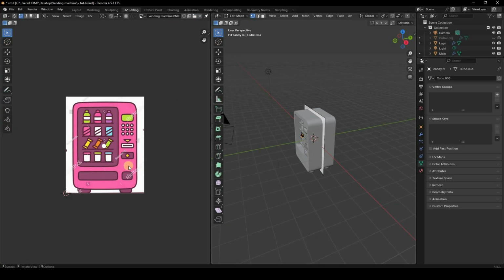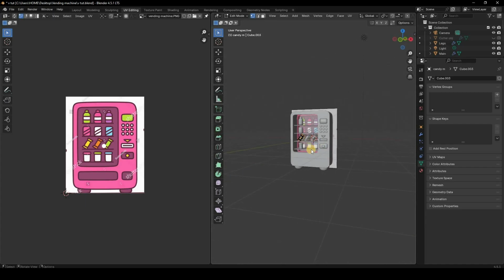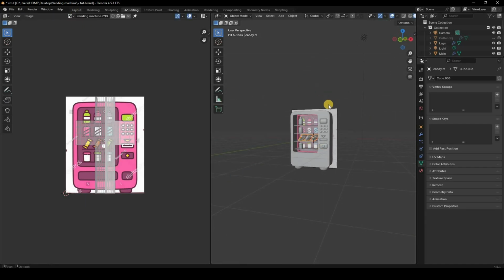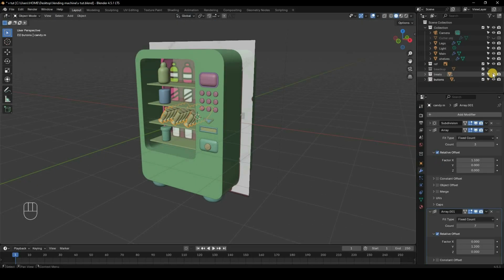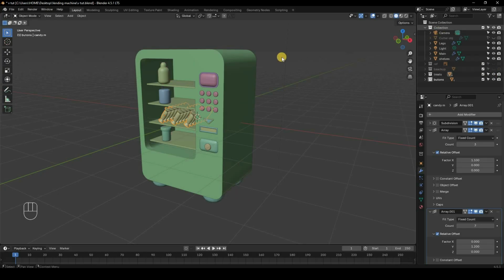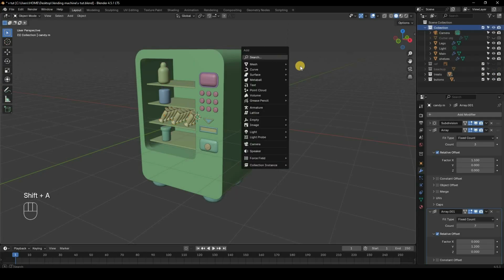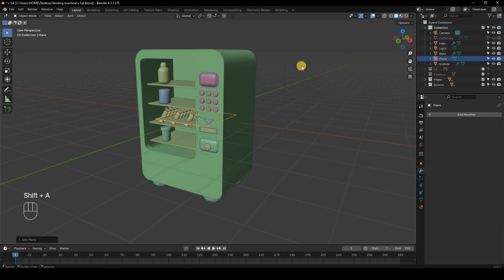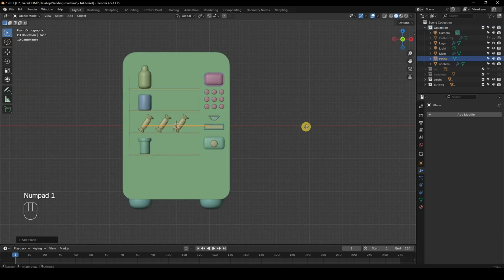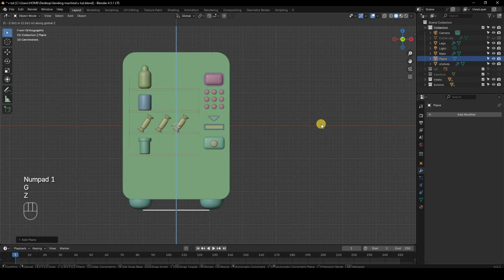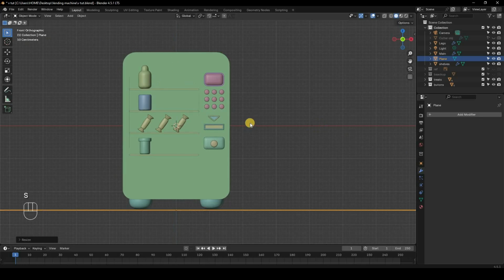So with 3D, what you need to know is that when you actually add a color, unlike 2D, the color will actually be reacting to light, which will in turn result in a slight difference in color. I'll just go back to the light, and I forgot to do one thing. I'll just turn off my reference for now, and I'll just go into the main collection and add in a mesh and a plane. This is actually going to be our background. I'll just move it down over here, and I'll just scale it big.